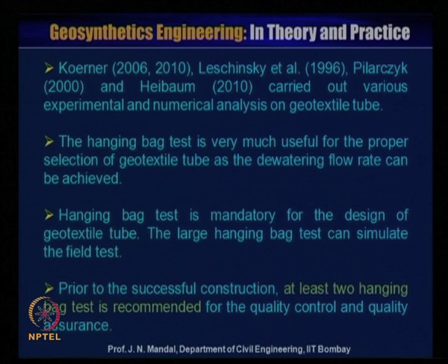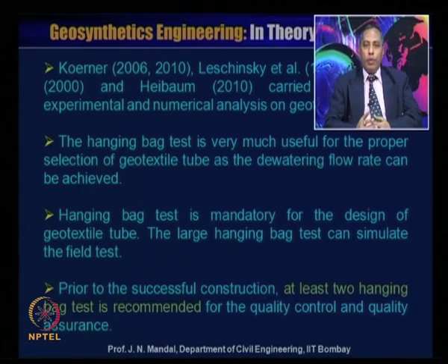Now, Koerner 2006 and 2010, Lee et al. 1996, Pilarczyk 2000 and Heerten 2010 carried out various experimental and numerical analyses on geotextile tube. We have also performed some numerical analysis on geotextile tube. The hanging bag test is very useful for the proper selection of geotextile tube, as the dewatering flow rate can be achieved.